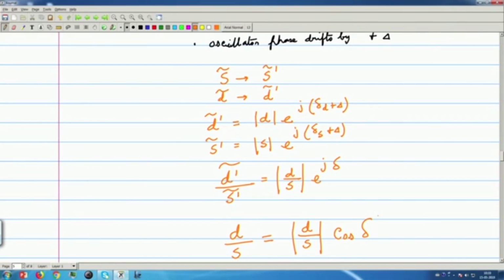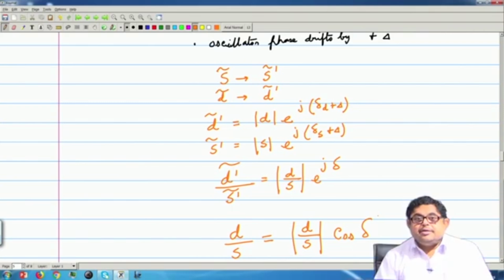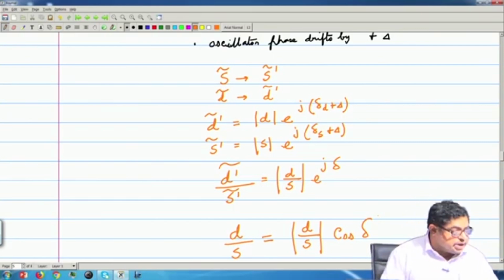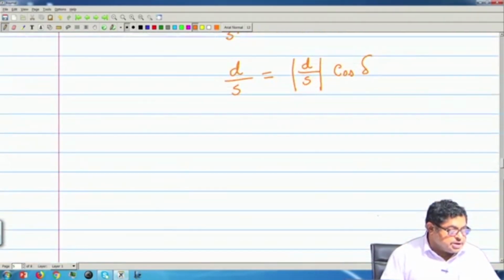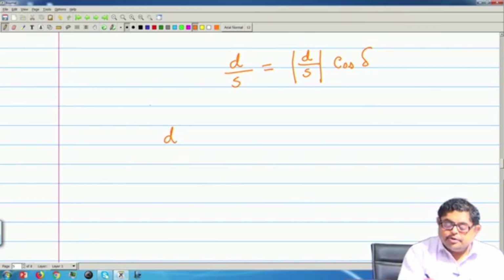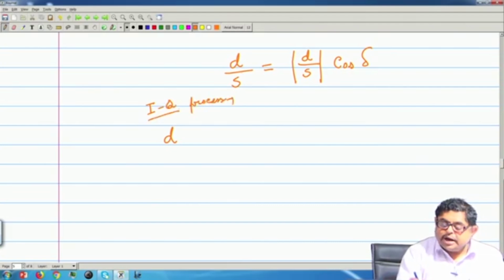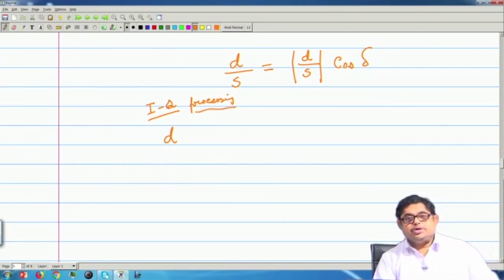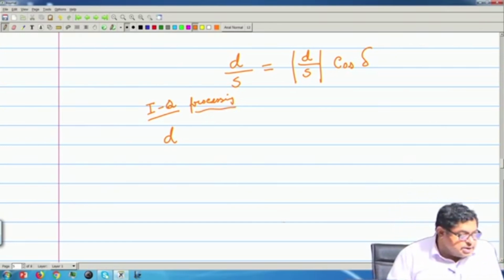Some radars in the receiver have in-phase and quadrature components. So, there this ratio will change, but the concept will not change. I will also mention IQ processing. The receiver is an IQ based receiver; actually most of the modern digital receivers are like this. So, this concept also should be seen.